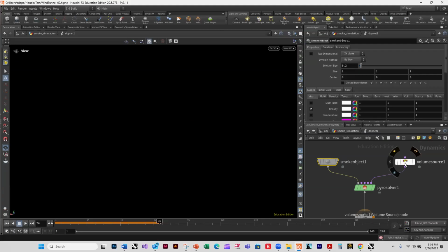So this is the internal storage of the Pyro solver. And that is the inputs that you generate to get it going. So you create a temperature field and a density field of smoke to start the simulation. The initial values that you input get placed in long lists that are kept in the memory of the solver. There are two copies of the information.